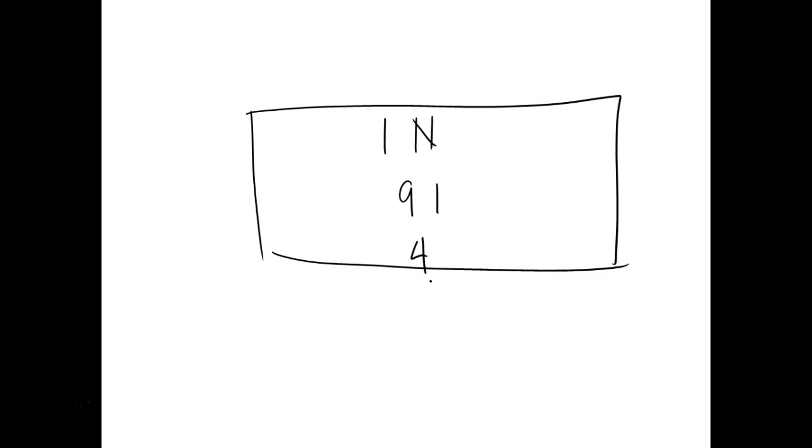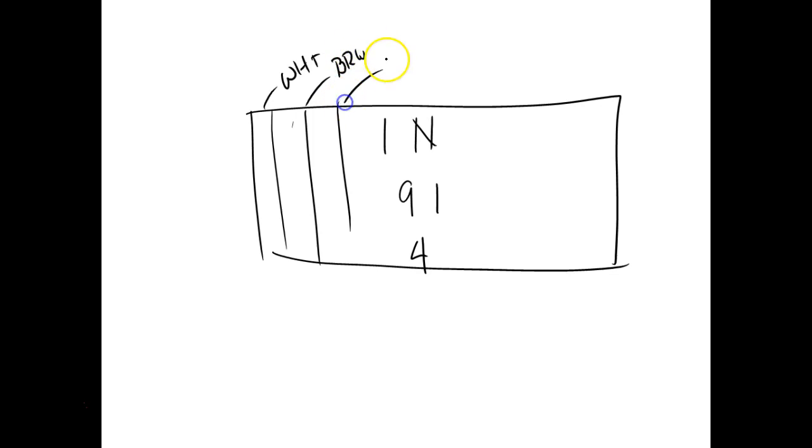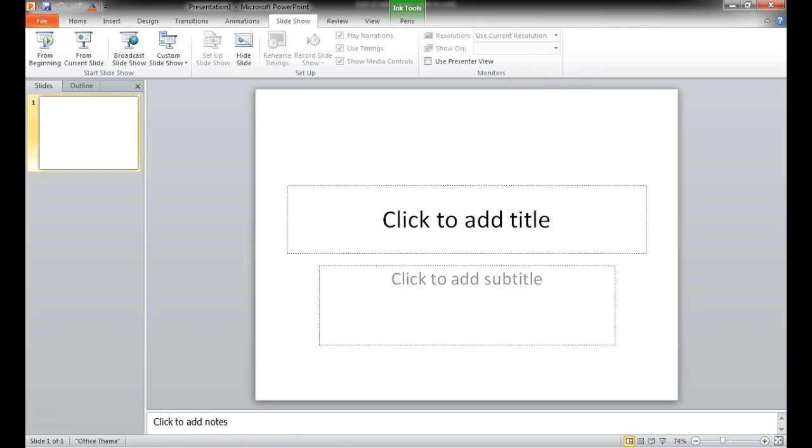But sometimes they do the color code. They'll put it on the cathode end, and they'll put a three-band color code, right? White, brown, yeah. Some of y'all might get the color code on there. We use color code a lot, besides just for resistors. We use the color code on capacitors, and a lot of capacitors have color code. We use the same color code on inductors. Once you learn that color code, you can use it on these other devices. I didn't see the data sheet there, so let me bring up Blackboard real quick.